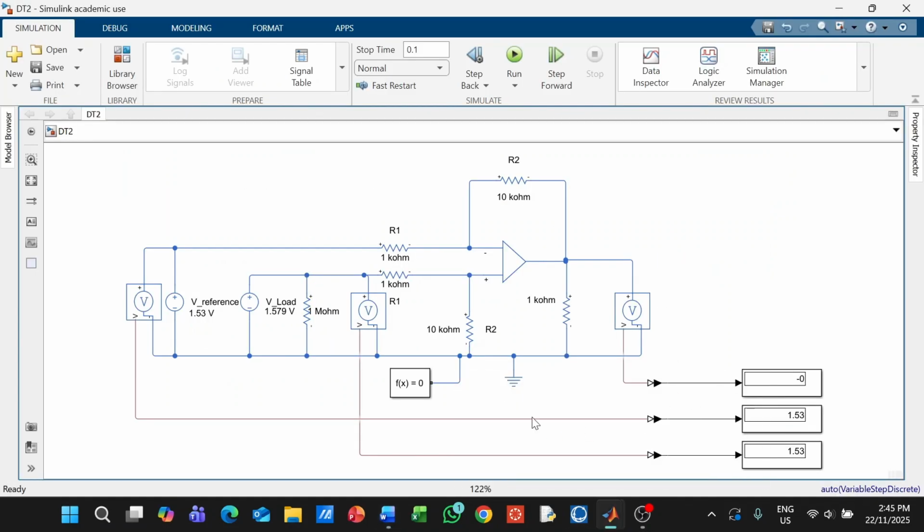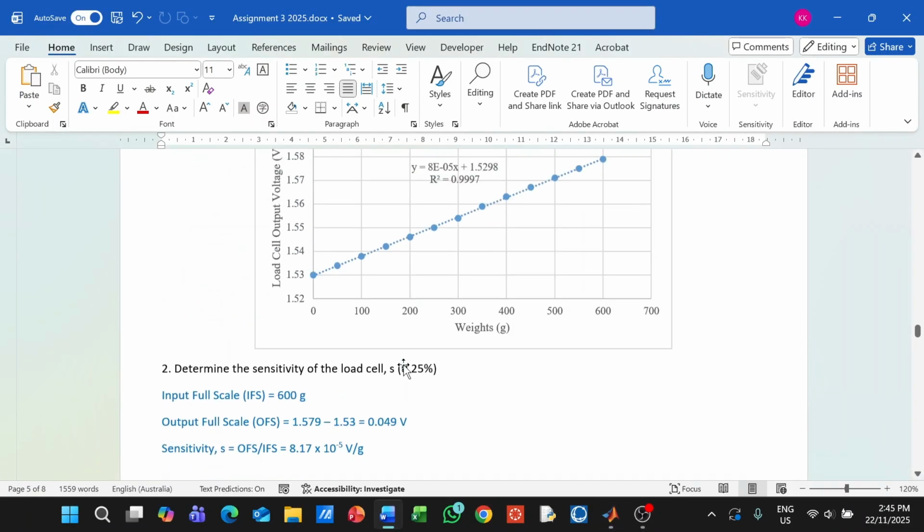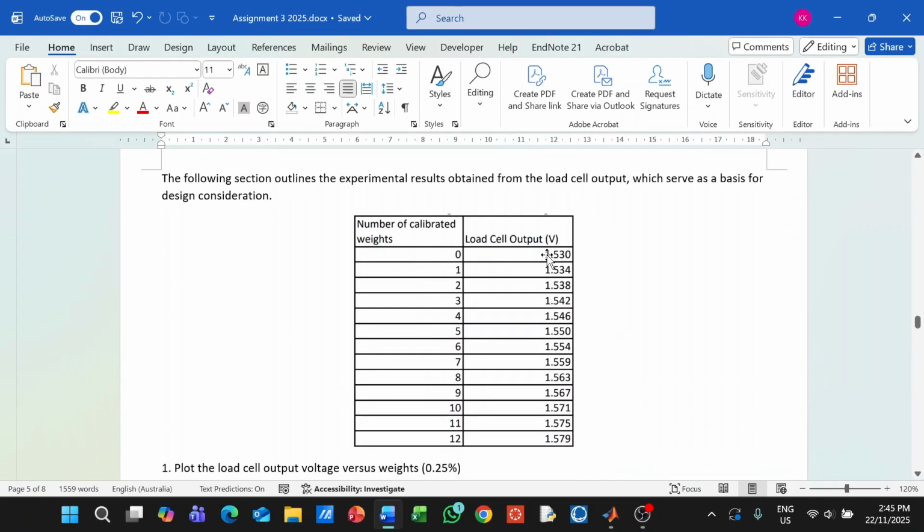And this is the signal conditioning circuit design, which will produce the voltage signal compatible with the DAQ system. The sensor voltage should be offset by a reference value, which I set to be 1.53 volt, which is the voltage when there is no load input.